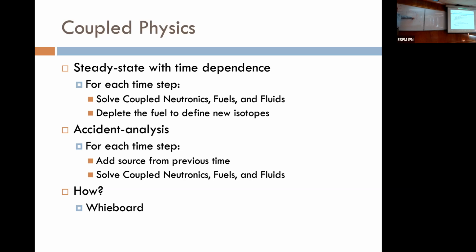Because I had a high temperature in the center. And so then when the temperature solve says, hey, I have a low power here in the center, now let me give you a low temperature. And you just iterate back and forth between them. And it gets into this oscillation mode where it goes from cosine to basically a double cosine. And you just go back and forth, and it never actually converges.